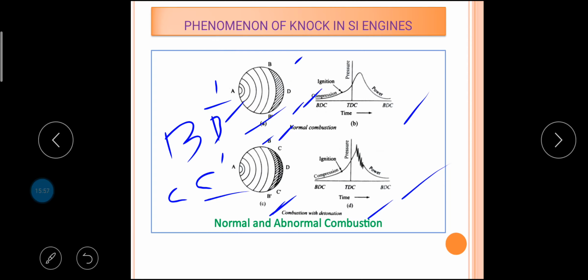The impact of knock on the engine components and structure can cause engine failure. And in addition, the noise from engine vibration is always objectionable. The pressure differences in the combustion chamber cause the gas to vibrate and scrape the chamber walls, causing increased loss of heat to the coolant.